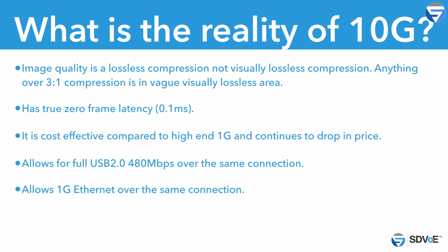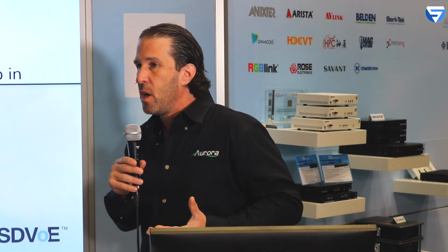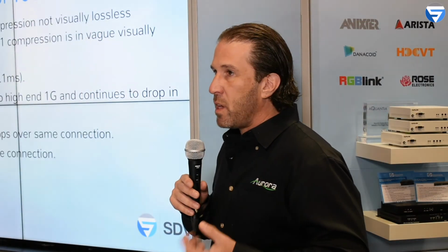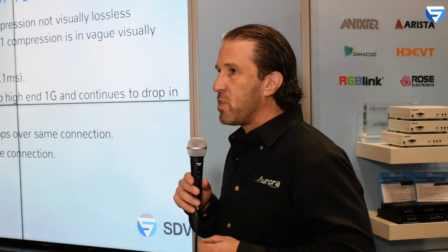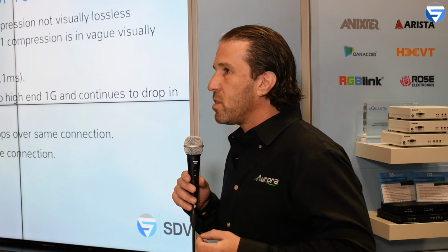Now let's take into account that USB 2.0 is a term that's very loosely used. Anybody can claim 2.0, but are you going to get the full bandwidth to deliver the cameras or the other high bandwidth requirements? If you're eating up over 900 megabits per second on the 1 gig LAN, how are you going to do 480 megabits per second of USB? It doesn't exist.